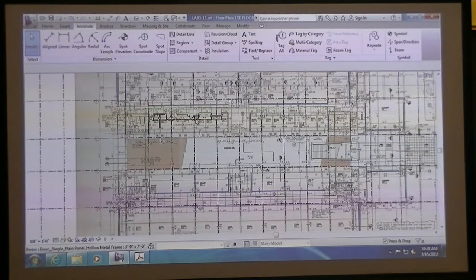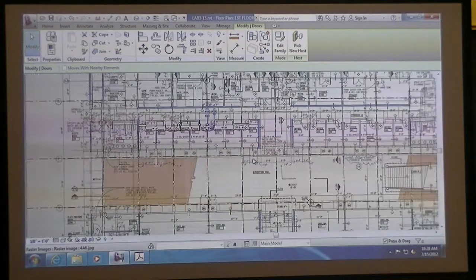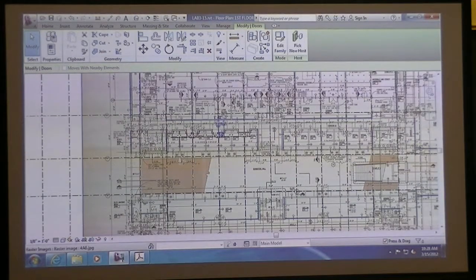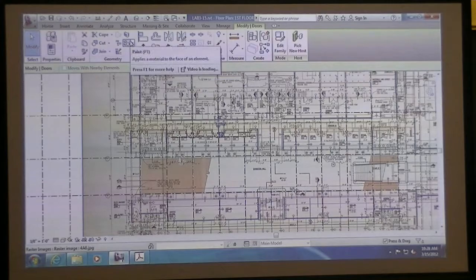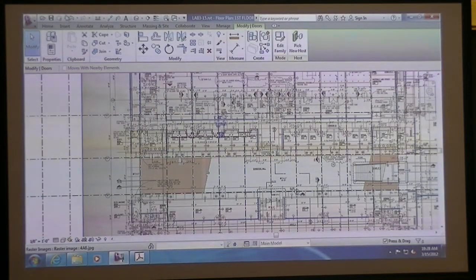For right now, just insert the door that we've talked about, the 3 foot by 7 foot door, and just go around and don't worry about the windows. There's some windows that you see, all these different openings. Wherever the windows are located, if this is a wall type 2, just draw a wall type 2 all the way through, and don't worry about the windows. We'll cut windows later. And do that for both floors, your first floor and second floor. Okay? And we'll need that for the start of next lab.